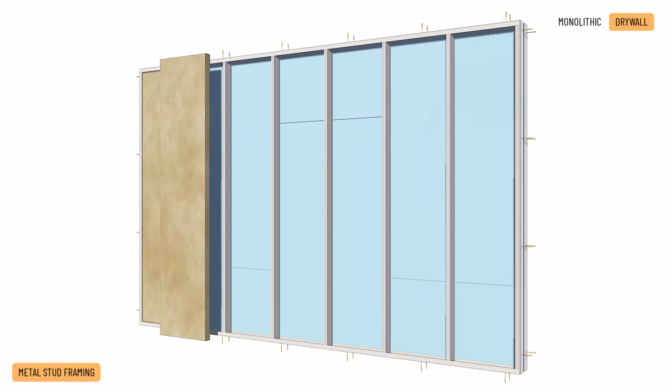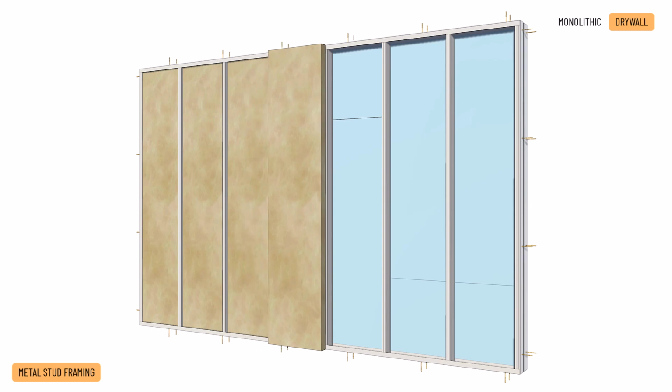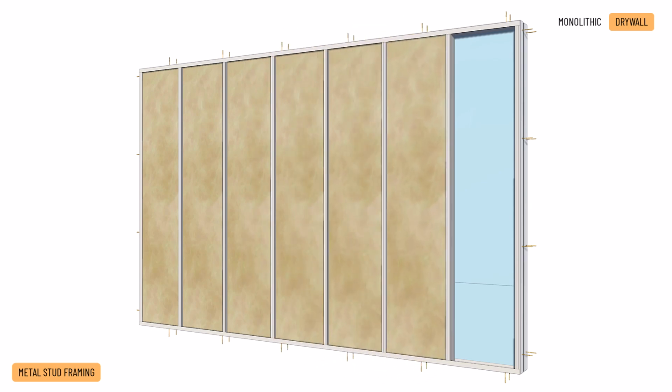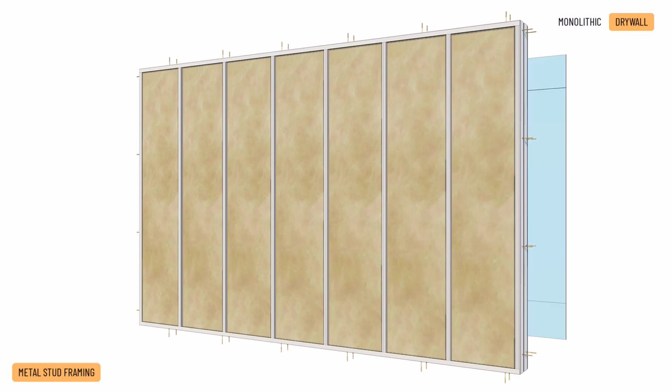8. The space between the studs is filled with rock wool insulation. 9. At the same time as the infill is placed, the necessary plumbing and electrical wiring for the building services will be installed. 10. Next, the gypsum boards are affixed into place with self-tapping drywall screws.